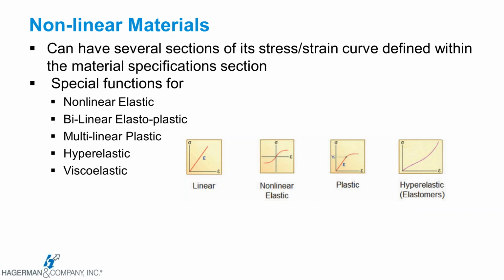And obviously, we have to go into the system and start to define those values. So there are different types of materials and different types of curves. Plastic, for example, has a Hooke's law section in the elastic stage, and then starts to become plastic after that specific yield point. Non-linear elastic, as we start to push and pull on those components, has different compression strengths versus different tensile strengths. We get into hyperelastic components, where they change their elastic states based on the loading.